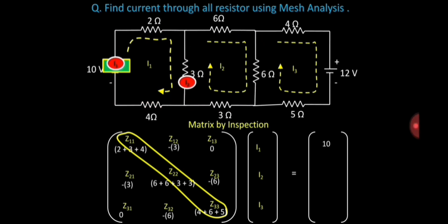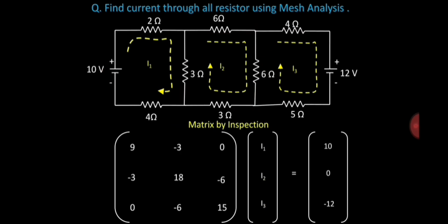You can see we have the resistors, but no voltage source present, therefore we'll have the 0. So going to the loop 3, we have 12 volts, but the current is traveling in this anti-clockwise direction. So as you can see, it's traveling in an anti-clockwise direction, so we have to label it negative, so it will be negative 12, and this one will be the complete matrix.